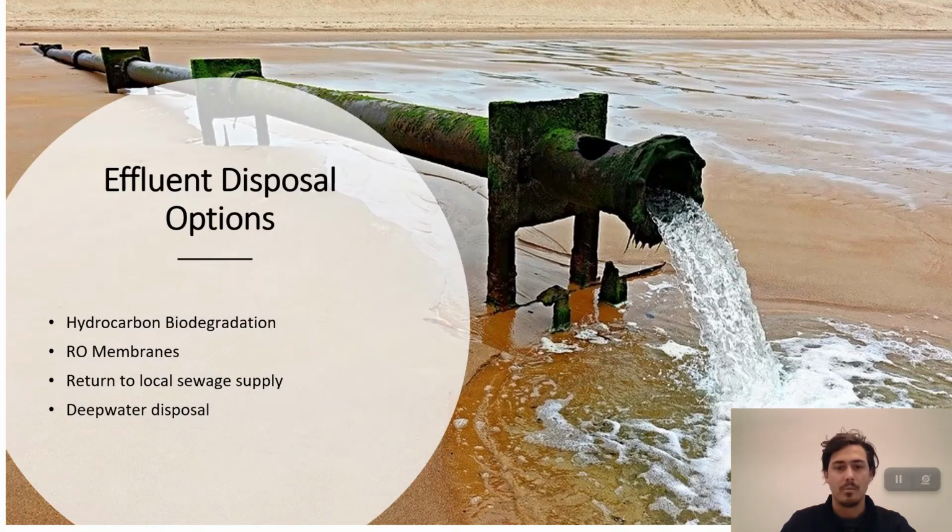As mentioned earlier, all petroleum refineries should have wastewater treatment plants to treat aqueous waste streams. Hydrocarbon biodegradation by biological or chemical processes, along with reverse osmosis membrane units, can remove up to 90% of contaminants in waste streams. This water can be recycled or reused in different stages of the process. The effluent can then be disposed back into the environment or main sewers if it meets environmental parameters, as long as it is continually monitored. Any hazardous effluent streams that are removed from site by sucker trucks need to be tracked with correct documentation.